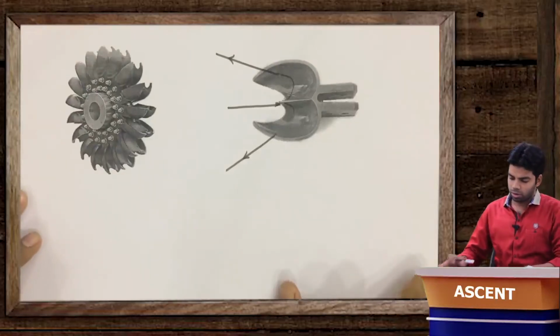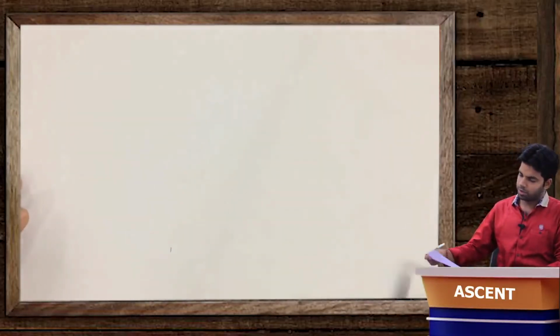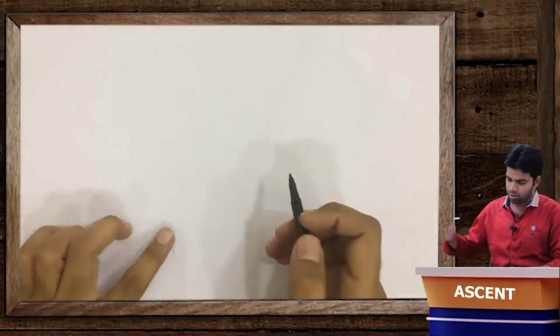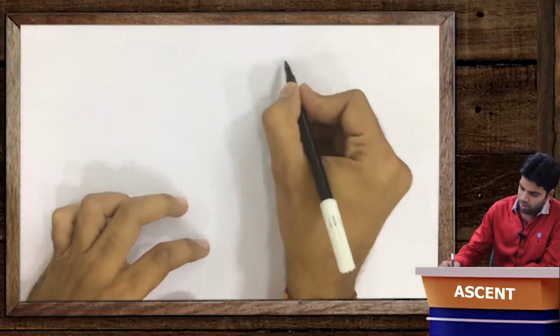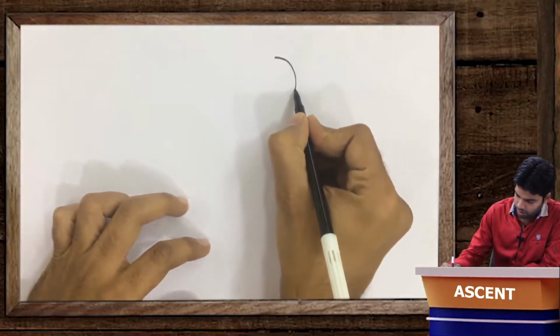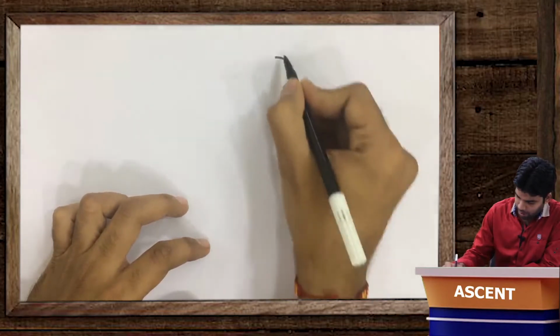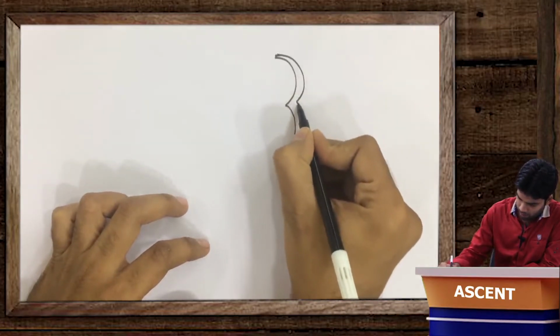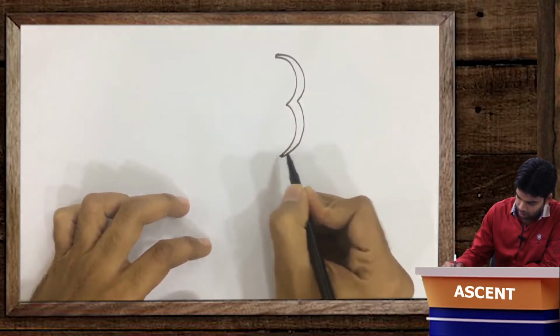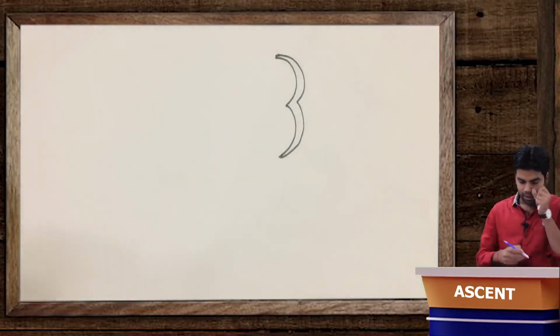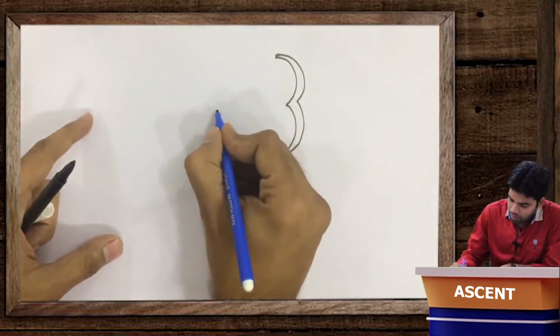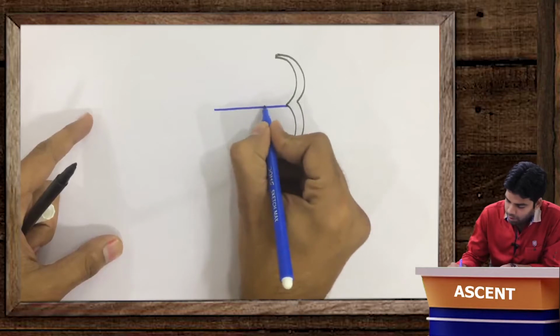Okay, so now we will draw the velocity triangle for this. So how would be the velocity triangle now? So we will draw the vane here, the blades. As I told you, it is double ellipsoidal in shape. Okay, and the water jet is entering from this point.